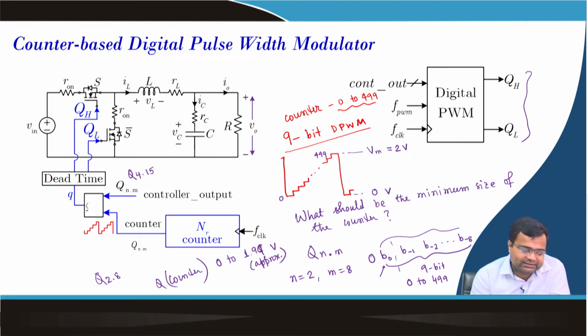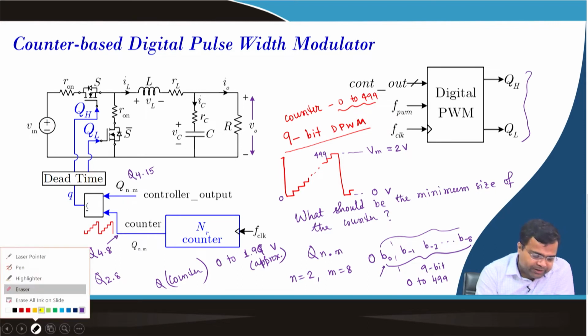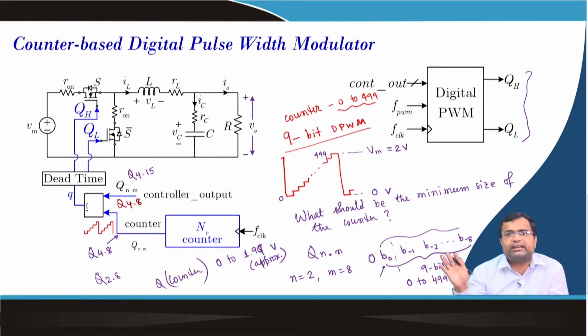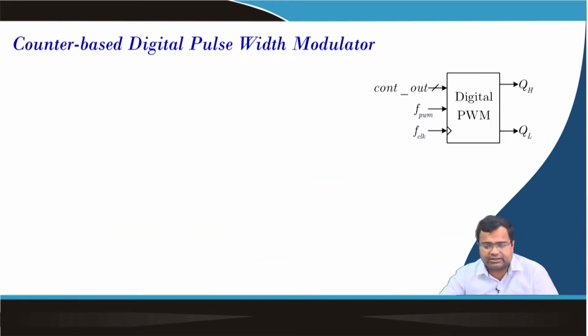In order to match, this counter must have 4 in the integer bit, and we can simply make 2 additional MSB by sign extension. So, this should be minimum 4.8 to be comparable. So, you need a resizing, and you can discard the bits to make this Q 4.8, where the 7 extra bits are discarded, and that we are going to discuss.